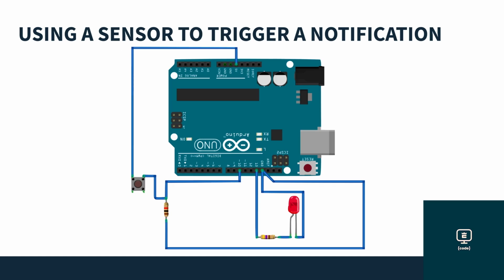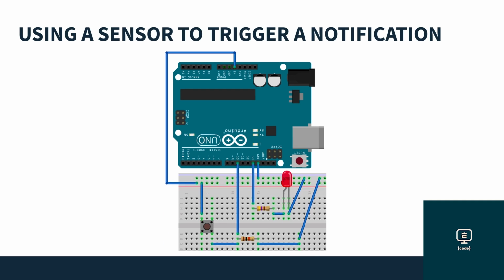So here's that circuit again. I won't spend too much time on this, but again, the 5 volts comes out of the power section, goes into the switch and into input 10, and it still has that pull down circuit. On the breadboard, same layout as before. If you need to review it, you can find pictures of both the circuit and the breadboard layout below this lesson, but you can go back to lesson 6 to walk through it step by step.